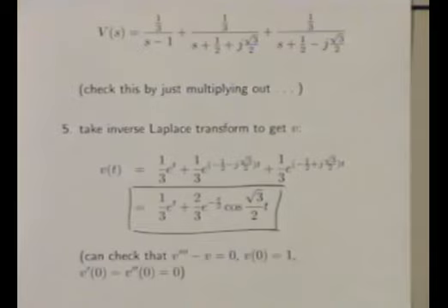But the way people have done it quite effectively for a while is by transforming things, and all of a sudden complex numbers are flying around, and there's impedances, and there's this and that. People are doing complex arithmetic, and then in the end you end up with a phasor, which is some complex number. And then you translate that back and you say, okay, the magnitude of the voltage is 315 volts, and the current is leading the voltage by 15 degrees. And that's the final answer. Okay? This is the same thing.